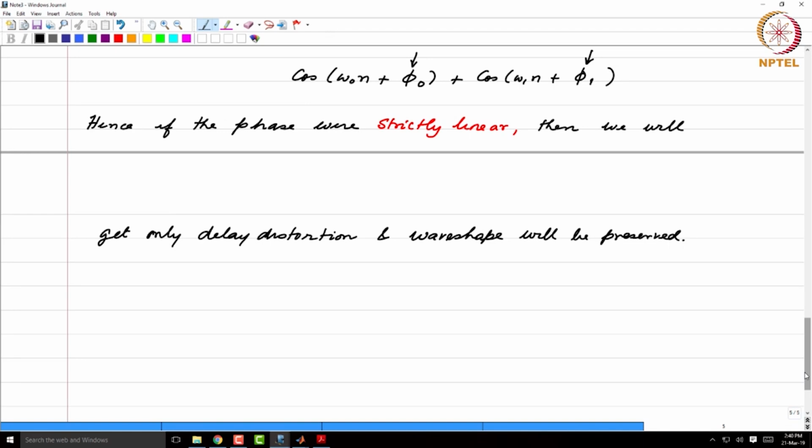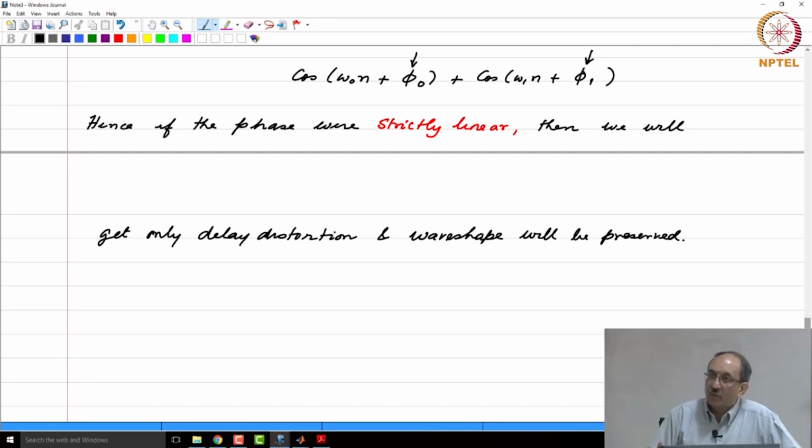And this can also be inferred from the definition of group delay. If the phase response is piecewise linear, then the group delay will be constant, and hence if the input has components that fall in the passband of the filter where the gain is nominally 1, if the phase were linear, then the output will be just a delayed version of the input. Because the phase is linear, and the passband being nominally 1 means the gain is 1, the gains are not altered for the individual components, and the output is merely a delayed version of the input for those components falling in the passband.